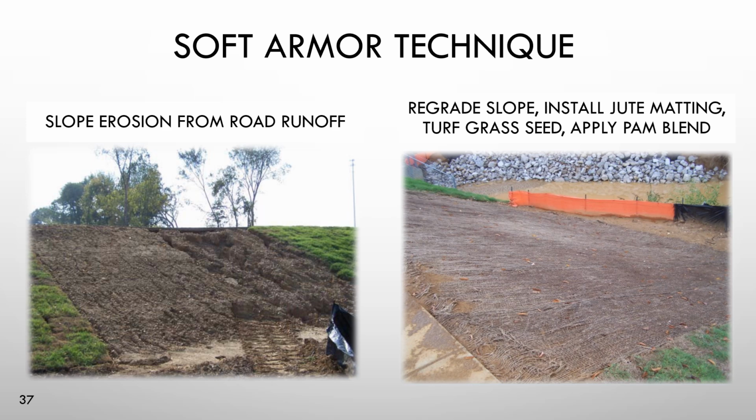They're going to dissipate the energy of that rainfall, help prevent erosion. But again, if we have fine clays and small particles, they're going to run right off, and we can have hundreds to thousands of turbidity even with an erosion control matting. So that's what that PAM is really used for: it's going to hold that matting to the soil surface and hold those fines in place.